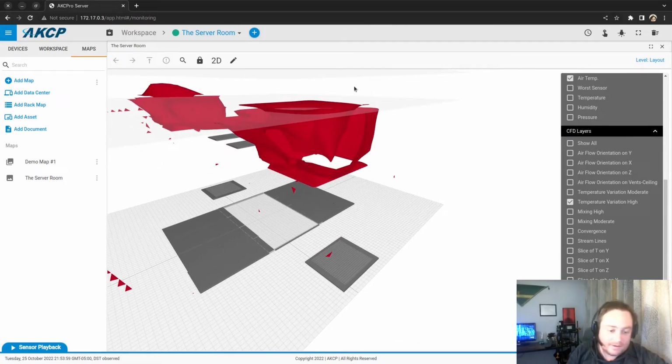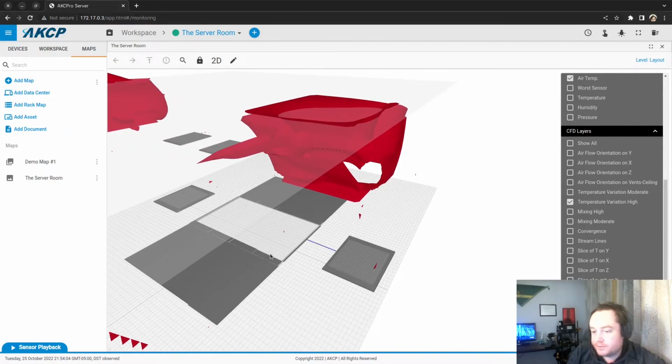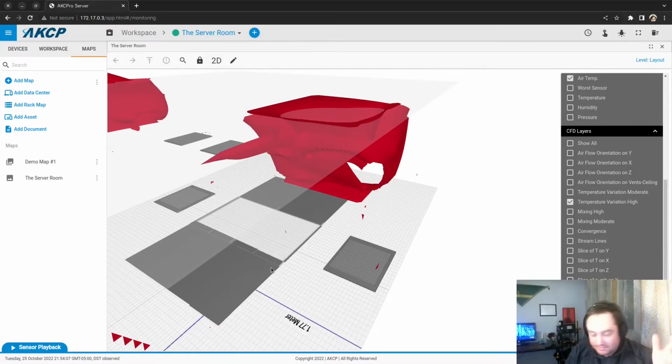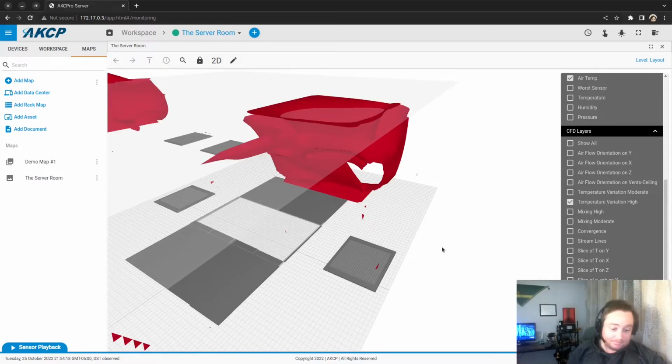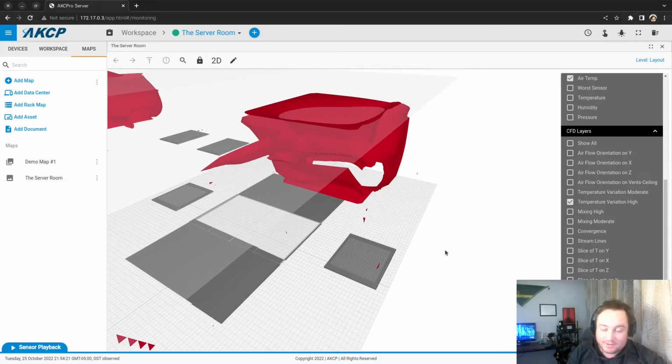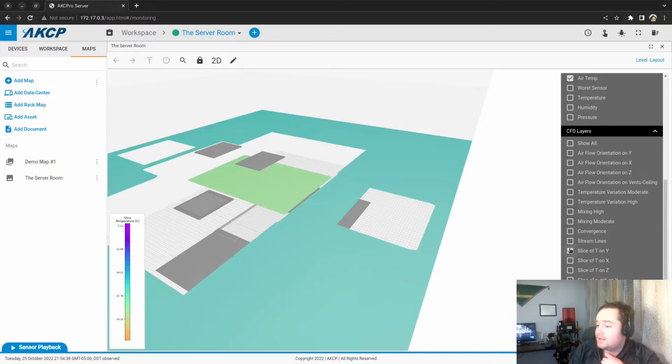If it's not a design mistake like I did, and it's in reality, maybe you have a gap under your rack and you drew it, so you can see that you have mixing in your air. So yes, you have all the tools. Obviously, the model is as precise as you draw it. If you have the probe installed and you make a mistake in your drawing, you will have some inconsistency. So you can detect already that something is not like you would expect.